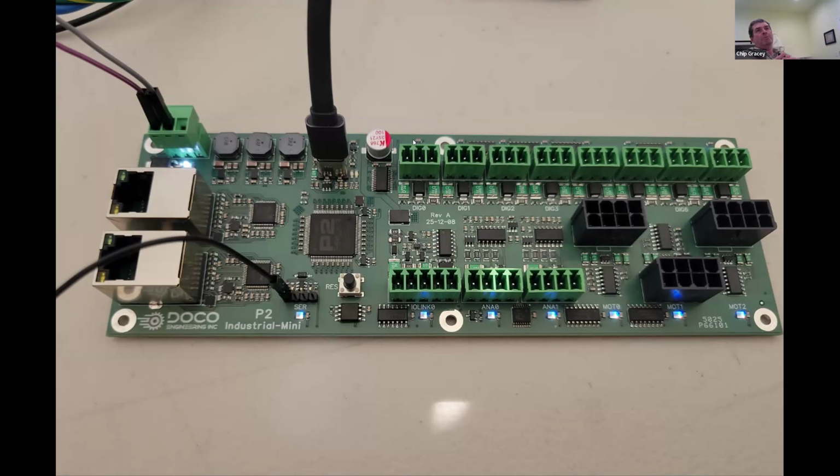Then I have a data bit which plays for 2-bit periods, right? That's high or low to represent data. And then we have another bit which is low. Always the last bit is low out of the 3. So we play the middle one twice. But this allowed me to decouple the states between the shift registers and what the LEDs needed, because it's a crazy thing. It's completely enharmonic. There's no rhyme or reason. And I was going crazy trying to make it all fit somehow. But anyway, I realized eventually I needed a little state mechanism that I can go out and get